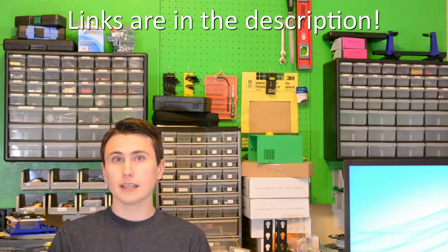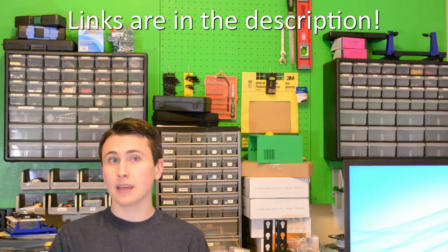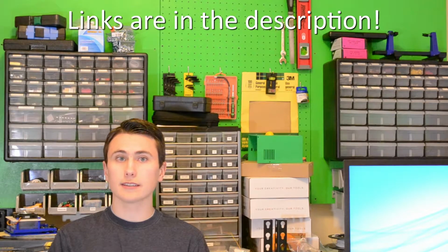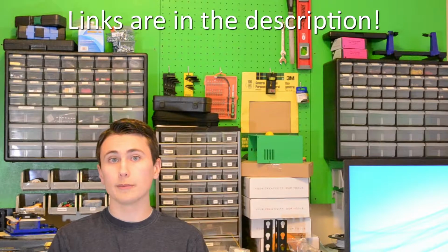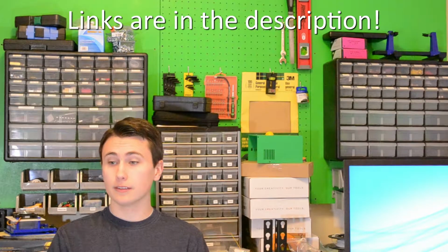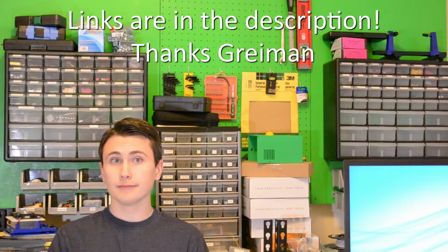I used a few libraries that really sped up my progress during this part of the project, and I recommend that you check out these libraries as well. First, I tried to use the Adafruit OLED library, but that didn't end up working out very well for me because I ran out of program memory due to the size of the frame buffer. Instead, I substituted the SSD1306 ASCII library, which is a much leaner library. If your application doesn't require images or animations, this library works really well. Thanks, Greiman.